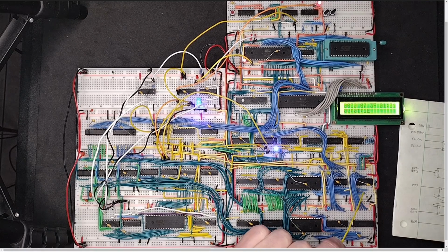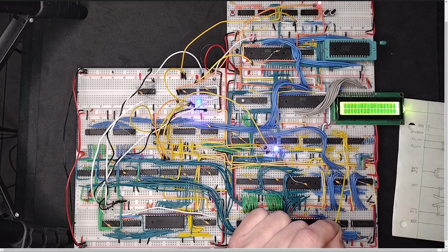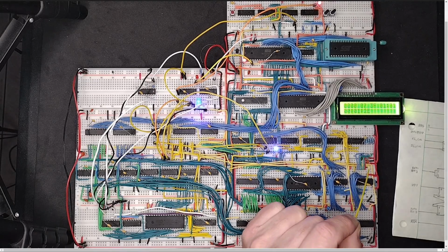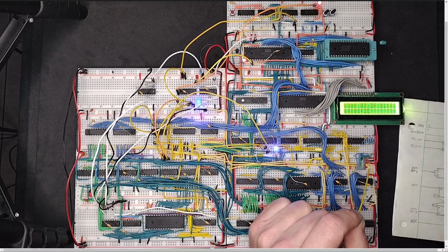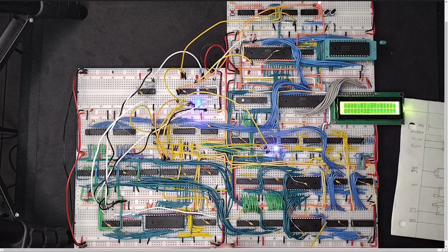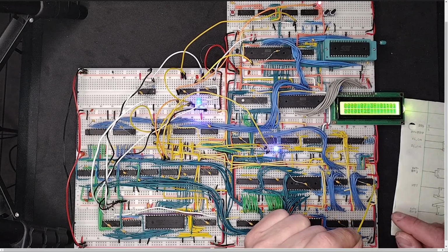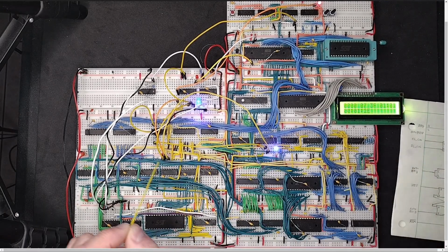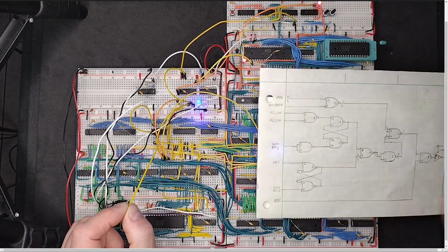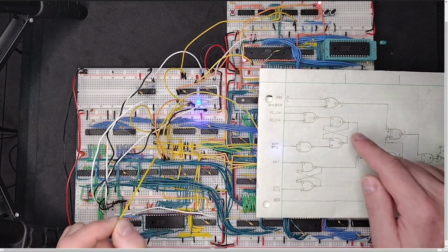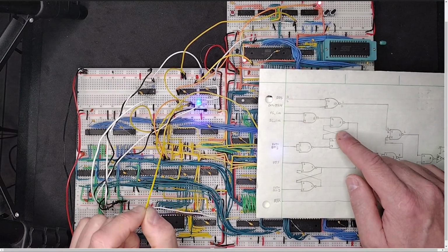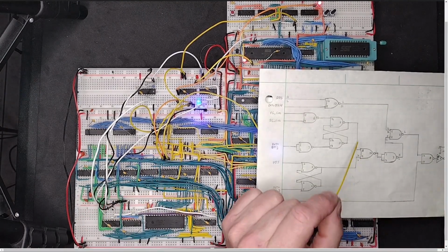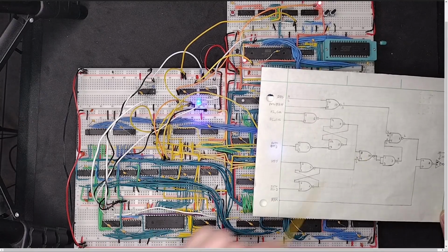Because we have an extra 2 bits in our Ben Eater video card, we're only using 6 bits for color. I use 1 bit to determine whether the foreground or background image should be displayed, and that's bit 7. I use another bit, bit 6, from each of the foreground and background RAMs, which is wired into this NAND gate. The output of this NAND gate is wired into the flip-flop, which then goes to the other half of this NOR gate.